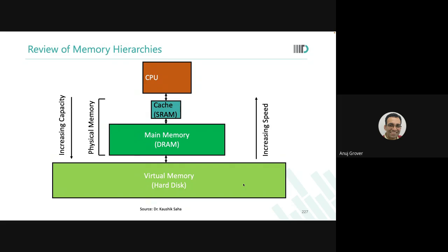You cannot say that there is no noise challenge there. There is a lot of risk because of noise, because it is not a CMOS circuit. All these reasons combine, and then that mismatch point also figures in. That sense amplifier offset doesn't seem to be reducing. It only increases with every technology. So where you thought you would be gaining performance, now your sense amplifier requires more offset. Your bit cell, whose current has reduced, now has to create a larger differential. And therefore, performance doesn't scale.